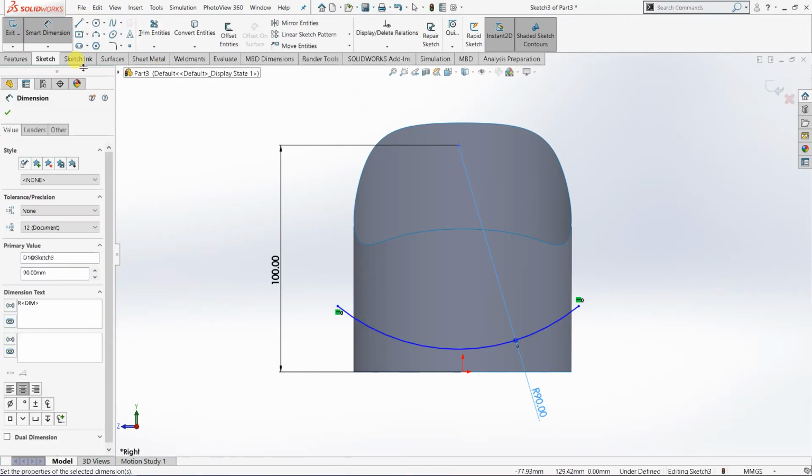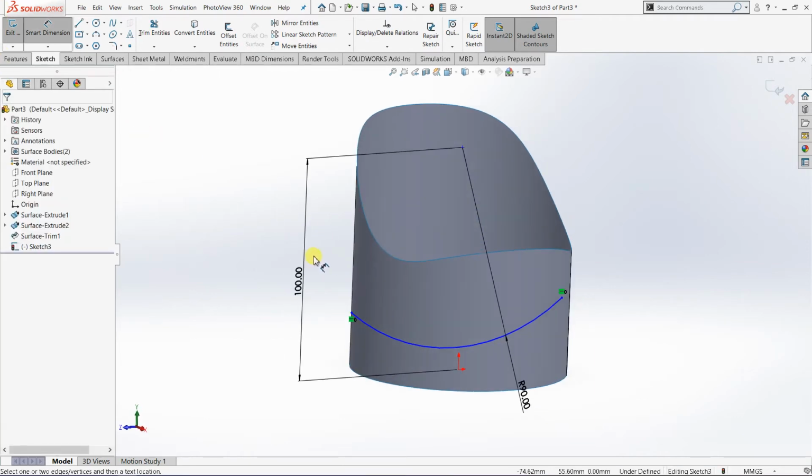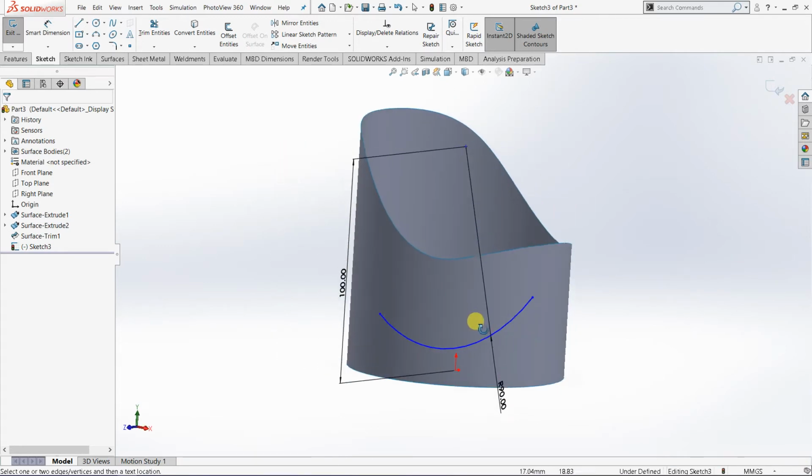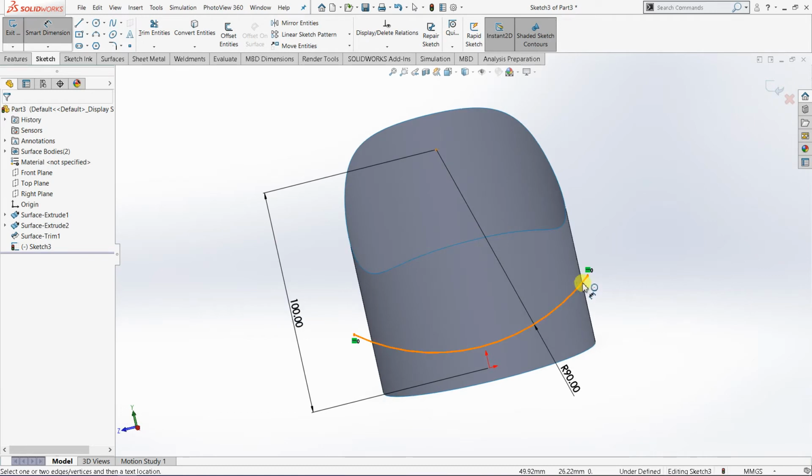There you are. You have to remember that in order to create the boundary or tool selection, you have to make sure it is protruded out, extending beyond the part that we're going to trim later on. So like this, it's protruded out.